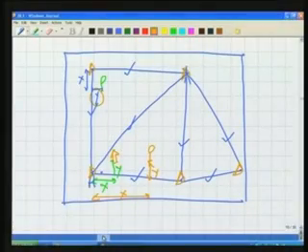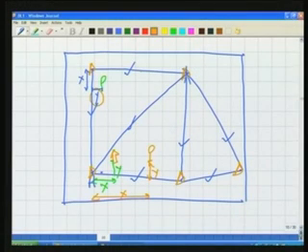The next principle. Now here itself, because what we have done, we have taken utmost care and we measured these lengths. What if some of these lengths are measured with error? What will happen in that case? Let us say this L3. When we measured it on the ground, we measured it with some error. If we measure it with some error, it will distort my skeleton of the area. All the measurements which I carry out later on will have some error now. My map will be distorted.